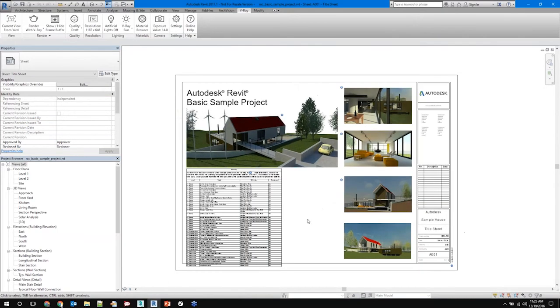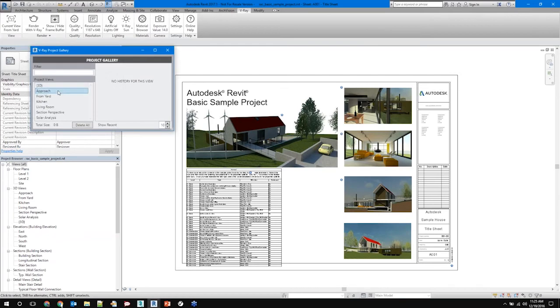and show you a little bit of what we've done in V-Ray for Revit specifically, and point out a handful of objects that are inside of the V-Ray for Revit interface that will allow you to get kind of next level imagery directly out of V-Ray for Revit. So over here in our renderer, this is the place where you would turn Swarm on and off inside of the renderer itself. We do have a project gallery, and the project gallery is going to save all of the imagery that you produce inside of your renders in a temp directory that you can pull up and see in the history here.